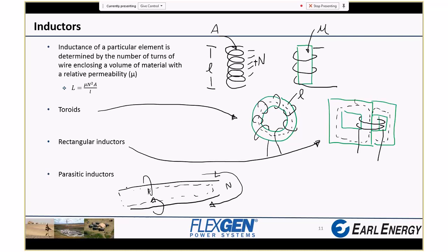So you see with wires, the parasitic inductance you get is very strongly related to the area enclosed by the wires. So running your cables like this versus running your cables like this, where they're zip tied together every foot or so, running your cables like this is a much smaller inductance than running them a few feet apart.